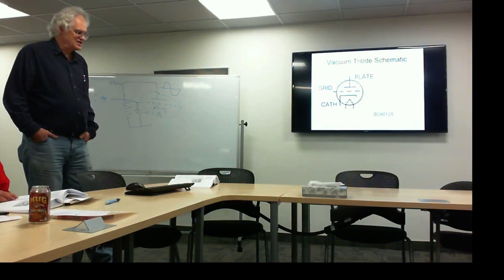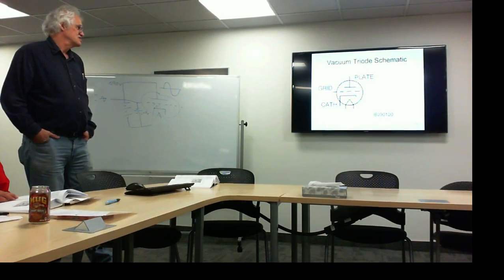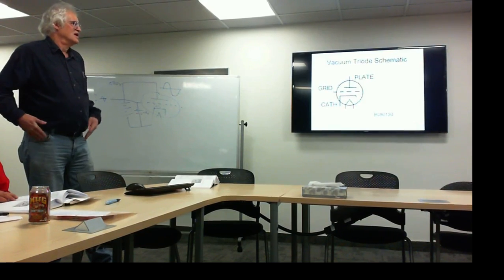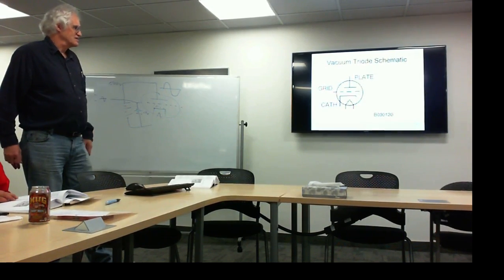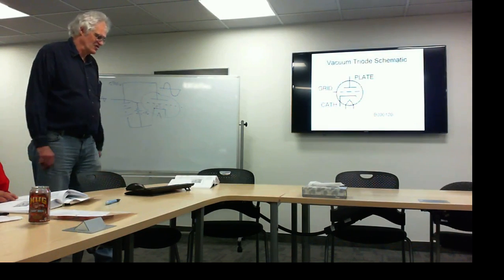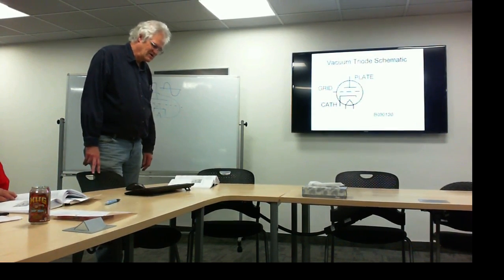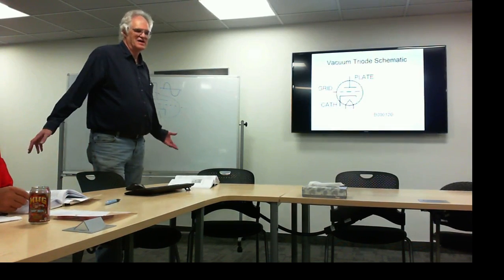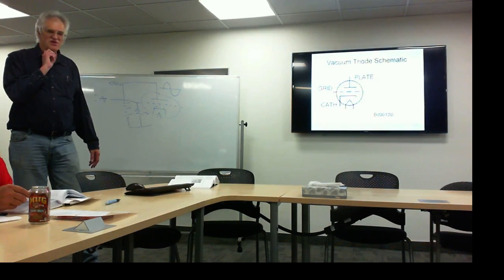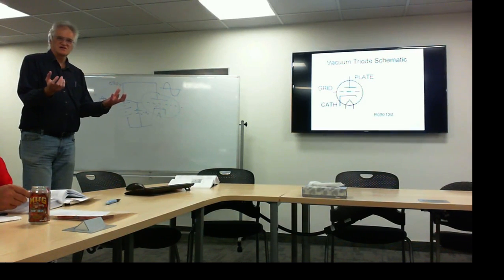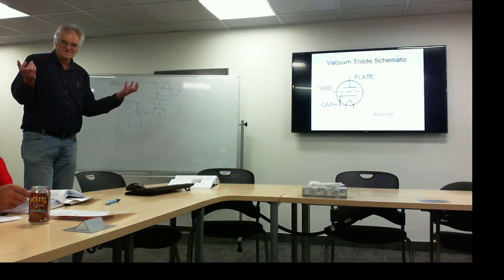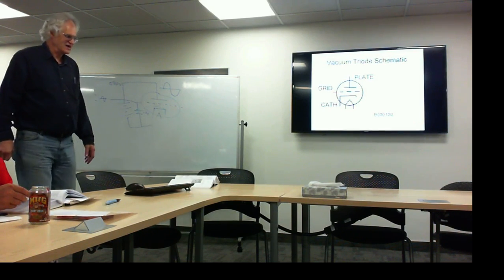Just some thoughts about tubes. One thing about them is that tubes are fragile, they break easier. You need a lot more voltage, a way bigger power supply to deal with them, in some cases 200, even up to 400 or 500 volts, to run a power amplifier. And the big thing about it is heat. They can generate lots of heat, and that was one of the biggest problems with tube devices. All the heat in the chassis would cook things. The capacitors would dry out and things would happen over time, mainly due to the heat factor.